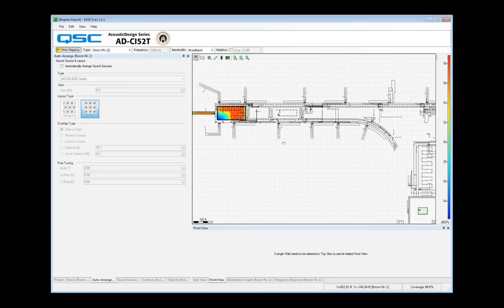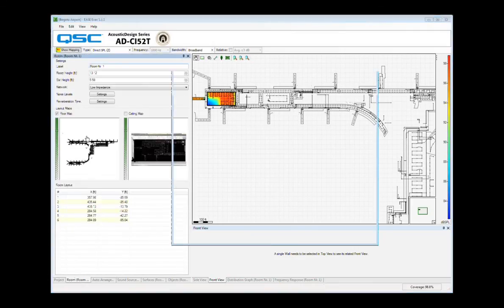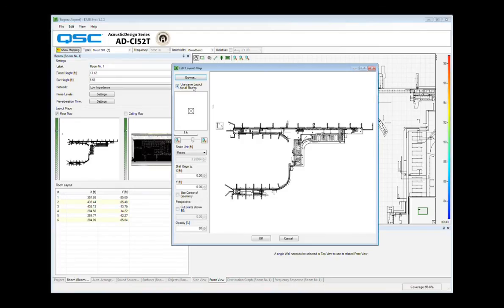So we want to divide this up. What actually ended up happening is that this was divided up into a number of separate projects. One of the things that we've done in the layout maps is allowed you to choose by default use same layout for all rooms. So we could do a project with multiple rooms with a single layout map for each room and assemble those all together. In a large project like this, when we're loading in 40 megabyte AutoCAD files, which is what the size of these files are, we get into a memory issue with all of those things. The project greatly slows down if we use separate layouts for each room. So one of the things we've done is gone to a common layout for all of the rooms, and this allows us to do some of these really huge projects that people are wanting to do.